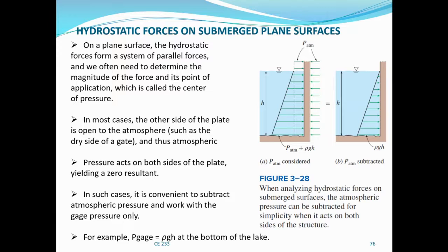Or you can visualize it just like a retaining wall, let's say in a swimming pool, let's assume. Okay, so on the plane surface, the hydrostatic forces form a system of parallel forces. These are the parallel forces, although these are the pressure force, the pressure acting on both sides. And we often need to determine the magnitude of the force and its point of application, which is called the center of pressure. The center of pressure is the point at which hydrostatic forces are applied.